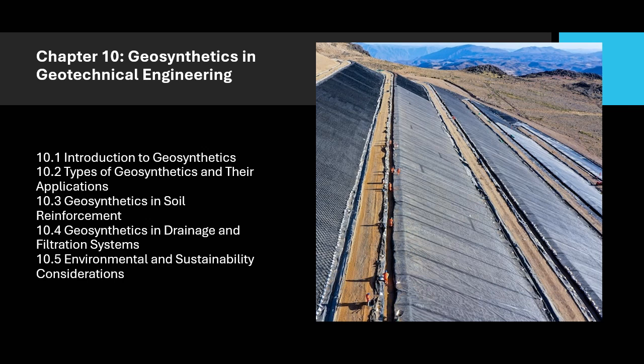Applications: 1. Separation. Geotextiles are placed between adherent soil layers, e.g., between subsoil and gravel, to prevent mixing and maintain structural integrity. 2. Reinforcement. Geotextiles are used to reinforce weak or unstable soils, such as in the construction of embankments, roads, and railways. 3.